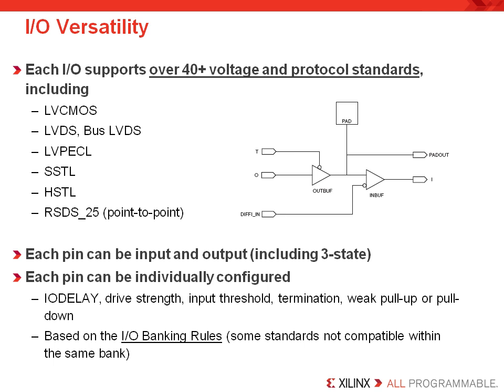The versatile SelectIO resource was first introduced with the Virtex family of FPGAs several years ago. It has been enhanced with every new product family ever since. I/O standards have been added and selected to support what our customers require. Spartan-6 FPGAs support over 40 I/O standards, including those you see listed here. But check the datasheet to see if your I/O standard is supported. That'll have the complete list.